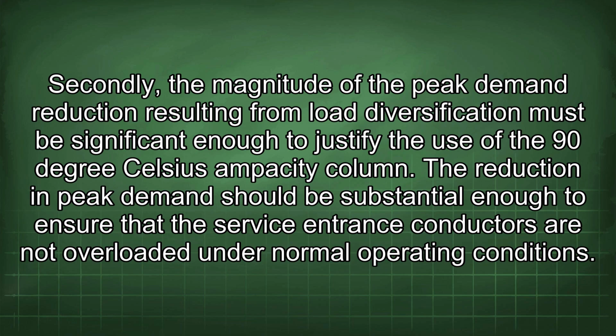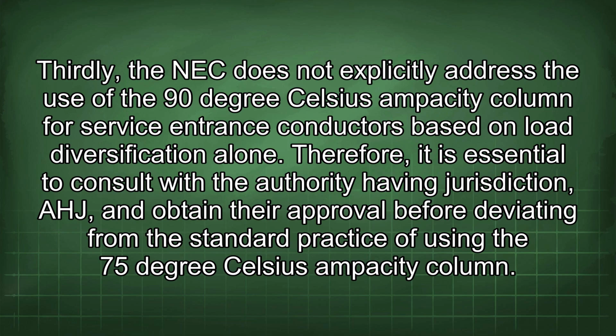The reduction in peak demand should be substantial enough to ensure that the service entrance conductors are not overloaded under normal operating conditions. Thirdly, the NEC does not explicitly address the use of the 90°C ampacity column for service entrance conductors based on load diversification alone. Therefore, it is essential to consult with the authority having jurisdiction (AHJ) and obtain their approval before deviating from the standard practice of using the 75°C ampacity column.